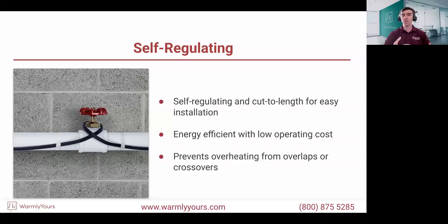it's already warm. It's more indoors, everything is flowing there, everything is good. That's where the cable is literally going to idle. So that's where the operation cost savings are going to get really visible, because you're not heating the whole length of the pipe at the same temperature, with one end flowing and the other end suddenly warming water you don't need to warm, for maybe your typical cold water pipe. So again, self-regulating is a really good approach here. Excellent.